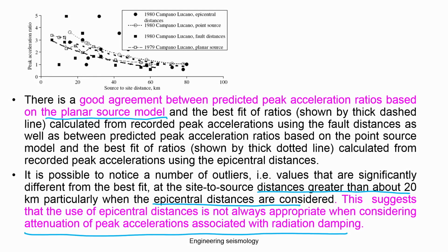If you want to design in those kinds of regions, you need region-specific simulation of ground motion, which considers the source parameters, the seismic moment, the quality factor and kappa, which are specific to the region. If you have to account for all those things, you need to generate or simulate the earthquake motions synthetically.